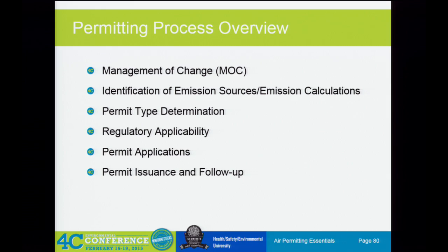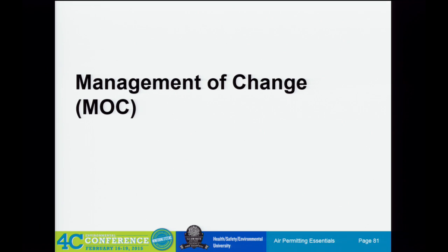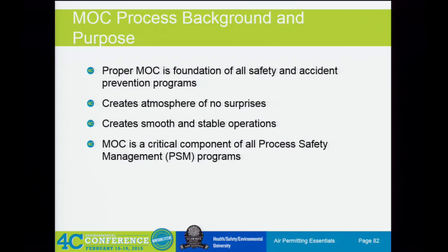So the first thing we'll cover is management of change, and then we'll get into the details of the rest of the permitting process. So the MOC process exists as a foundation for all safety and accident prevention programs. So every facility should have some sort of MOC process. It creates an atmosphere of no surprises. The environmental program should be involved in all MOC processes, and that way they know when a process change is occurring at the site that might trigger you needing a construction permit.